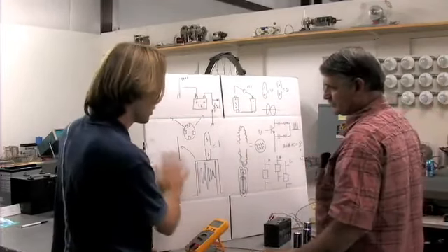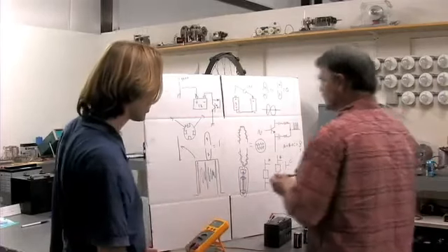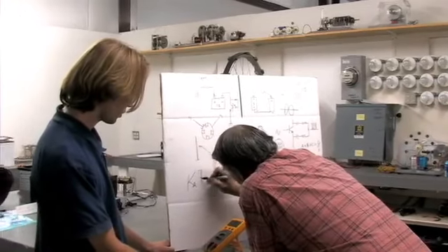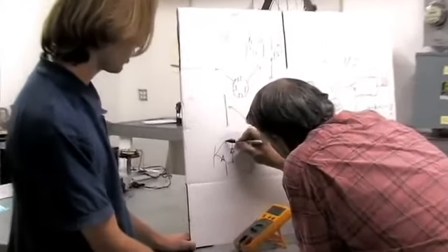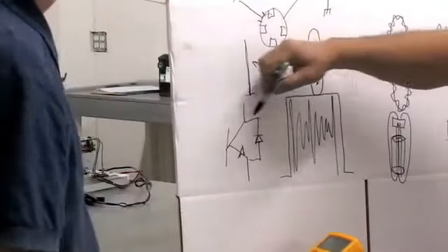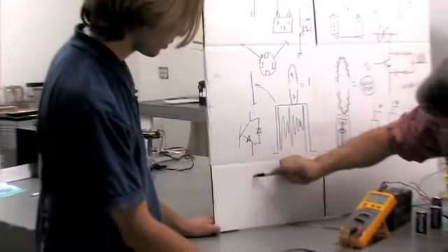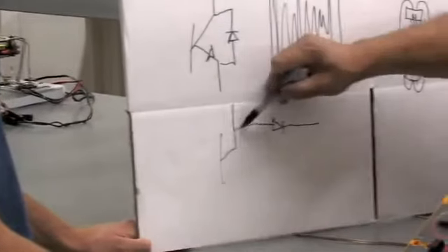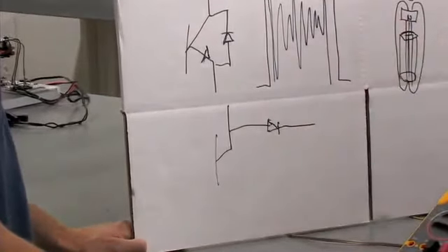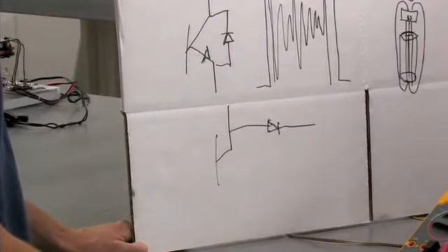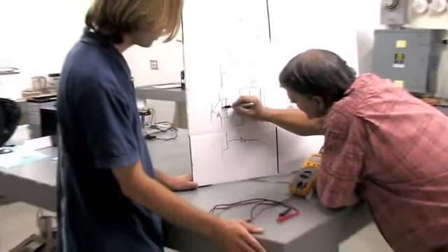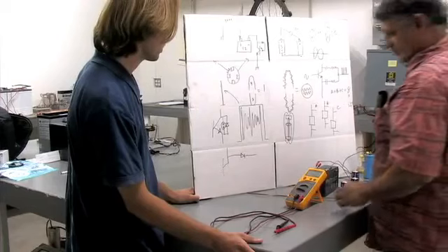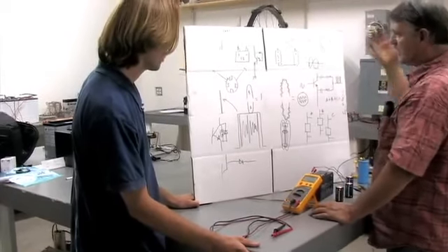So in conventional circuits, that all gets chopped off. Yes, in the conventional circuit, if they see that, they're going to short that out to protect this device. But since I'm taking it off, I'm just catching the spike and sending it to the battery. I don't have to protect anything. If I want to protect this device, I'm just going to put a neon light here. I'm going to limit it to 90 volts. And that's exactly the way I see it.